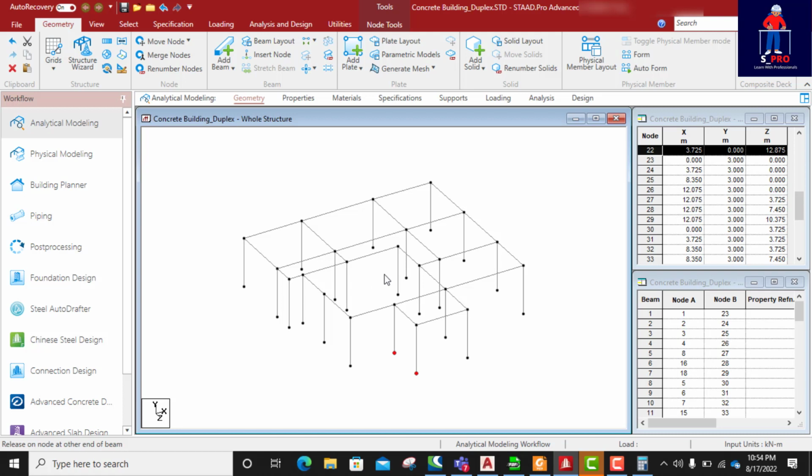But normally if I'm doing my design, I'll find a way. If increasing the thickness to something like 175, 200 can work, then I will leave it. But if it cannot work, the only thing is to introduce a beam in between. Okay, that's that.